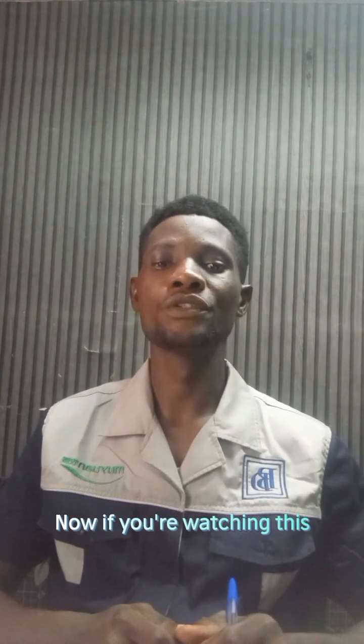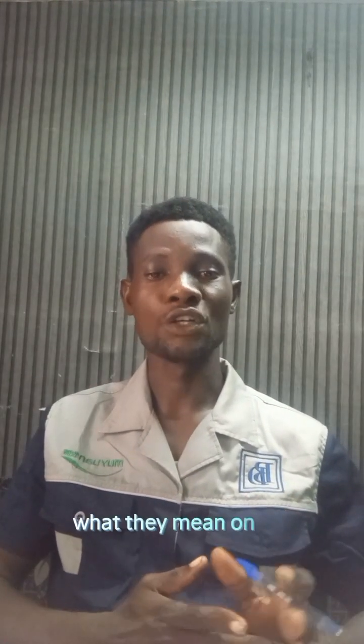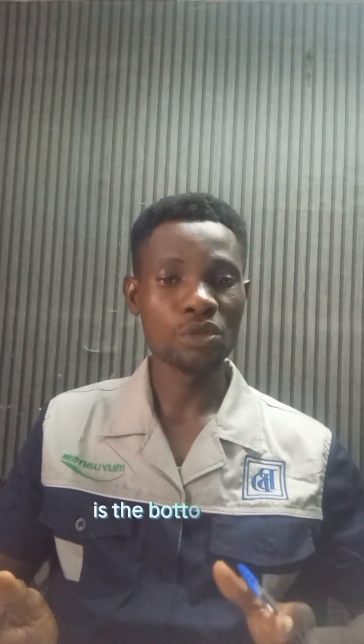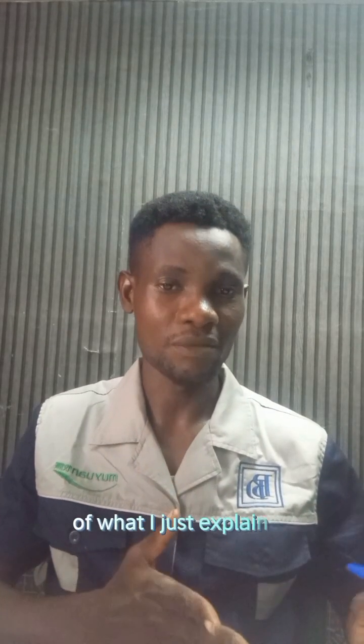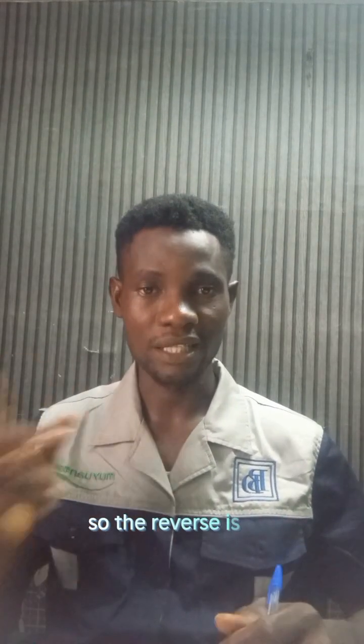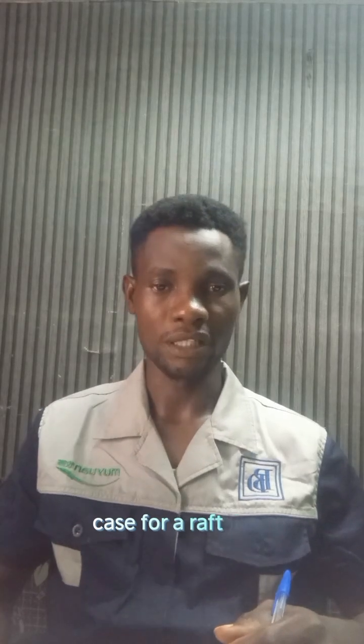Now, if you are watching this video to the end, kindly know that this connotation, what they mean on the suspended floor, is different from what they mean on a raft floor. I said the B1 is the bottommost reinforcement, the bottom reinforcement in the suspended floor, because the drawing I just used to explain is the suspended floor. But on a raft floor, if you are doing a raft foundation and you have a raft slab, the reverse is the case of what I just explained from the suspended floor.